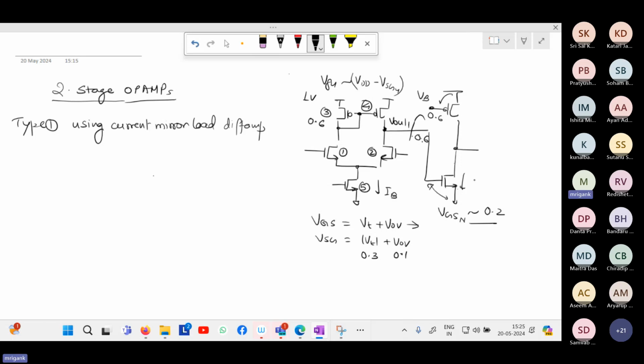And second thing is the output side. If you look at the lower potential, the minimum that you can get is VGS minus VT. So VGS minus VT is your Vout min. Now, since the gate voltage is higher, the lower side swing will be affected, so it will be lower than expected. So both things are there.